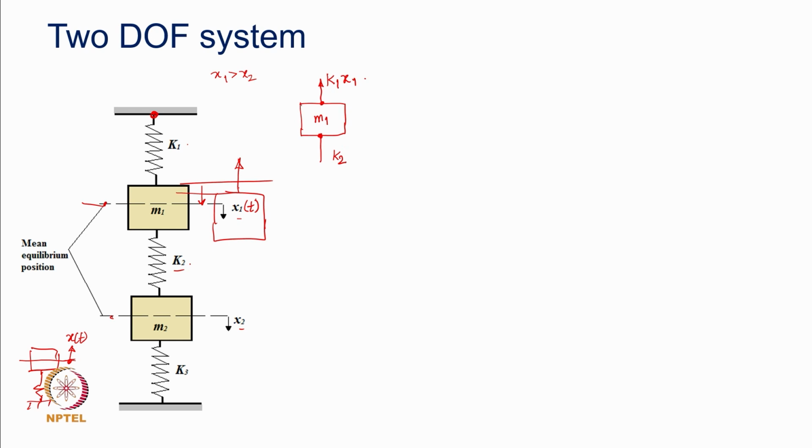And how much will be the stretch or the extension or compression in the spring? Make a note here that the springs have two ends, that means the relative motion of the two ends is going to decide how much is the effective force acting. So, will it not be x2 minus x1 or x1 minus x2? It depends upon in which direction you would like to keep it.